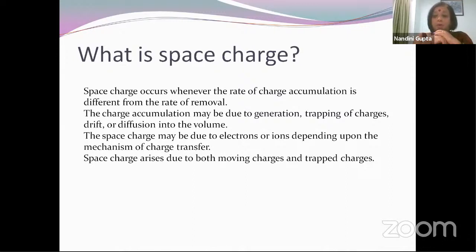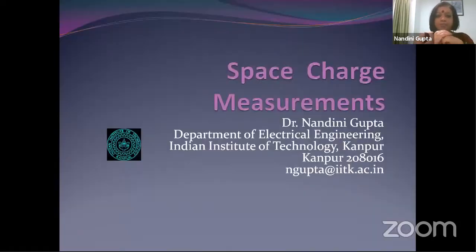And depending upon whether the high voltage electrode around which the non-uniform field happens is positively charged or negatively charged, you will have different kinds of corona. If it is a positively charged electrode which results in corona, you will see a whitish glow, a uniform whitish glow around the electrode or the transmission line.